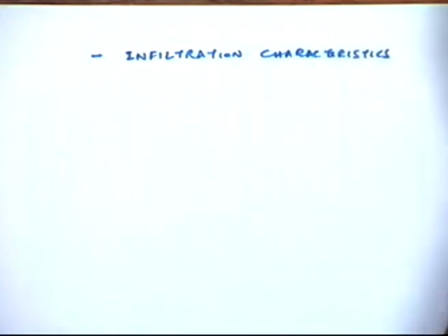What are the infiltration characteristics of the soil? And that is very important if you want to use the relationships which are known relationships. You might like to, because the infiltration which is taking place is dependent on the soil type, and if you can evaluate the infiltration characteristics, then you can use those characteristics in your formulations.